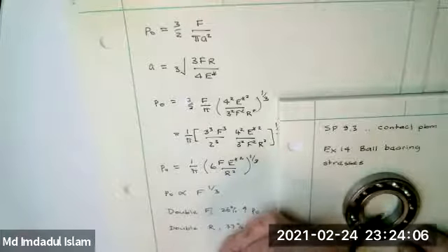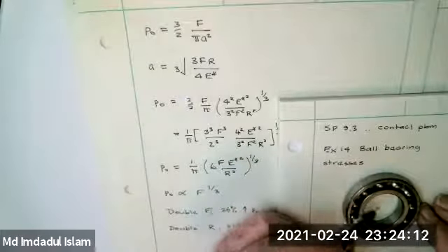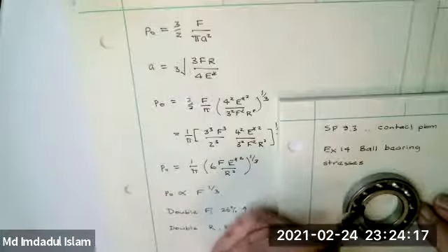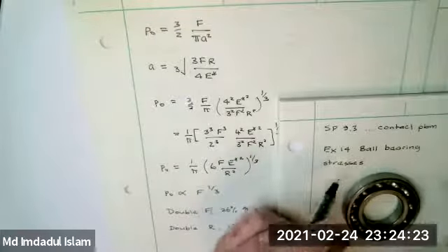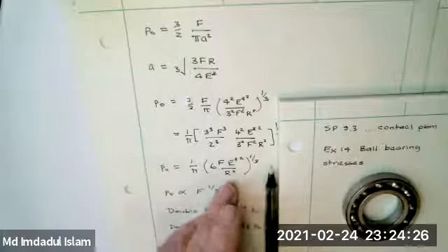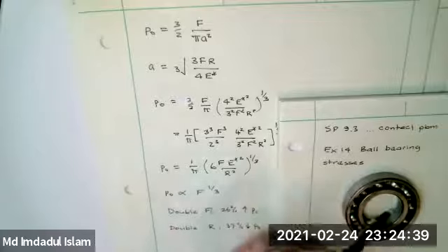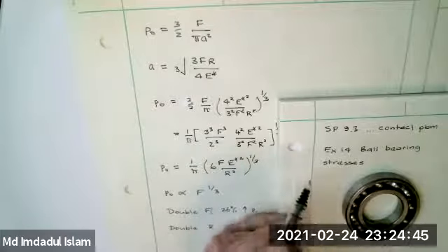Okay? There are some other rules. What's going to happen in practice is this bearing will have some rated value, and you can do catalog engineering. You can do that until you get something that fails, in which case you need to understand what went wrong. Well, when you're picking bearings, oftentimes in practice you'll do reverse engineering. Somebody has already picked that bearing, and if there are no reports of any problems, you just pick the same bearing. But when you start doing something new, you can get load capabilities of bearings from tables. But every so often something weird happens, and you need to start understanding what's going on with these. And so we'll do one of these problems.